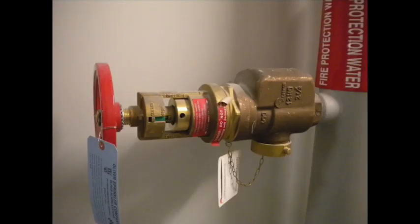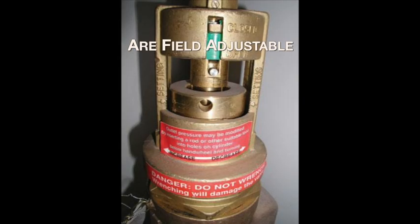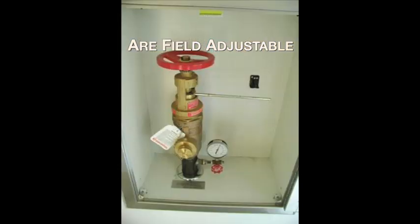Several newer versions of the pressure-reducing valve are being installed in buildings. These newer style valves are considered field adjustable by firefighters using an adjustment rod. During your pre-planning, the location of these adjustment rods should be identified, if not carried, in your high-rise bags. The way these devices are adjusted will vary with the manufacturer, but in most cases involve placing the rod into the opening and spinning the valve left or right, as indicated on the sleeve.